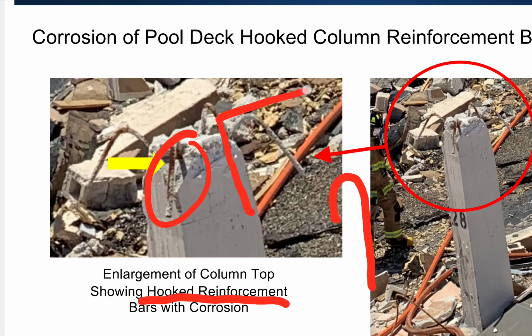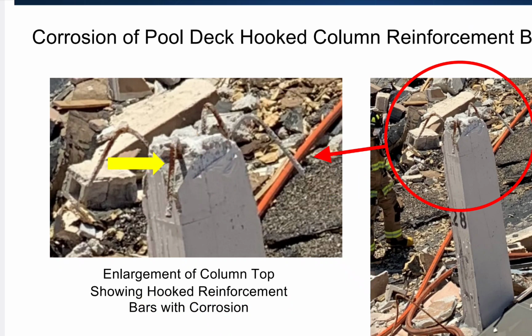This reinforcement originally were 90s. Little shear heads. All right, these were 90s, like that. I then call them rabbit ears because they're folded down like little rabbit ears. Look, see, like little rabbit ears? Folded down. And they're indicators telling us what's going on. Specifically, look at number 28, the scratch marks. I do a video on that. It tells you that part of this going across the deck, this reinforcement went over this direction to your right here, let's say.